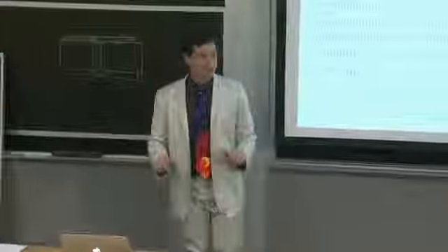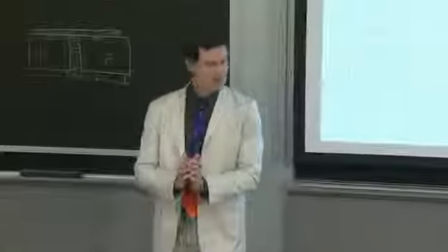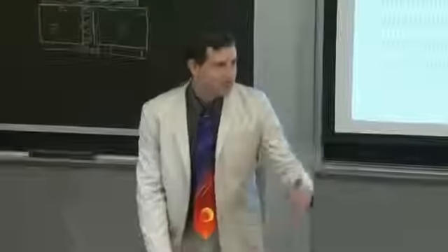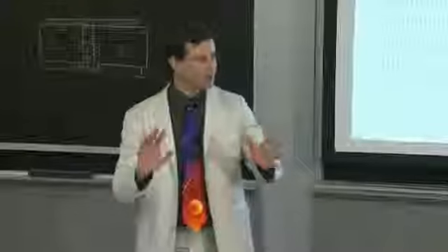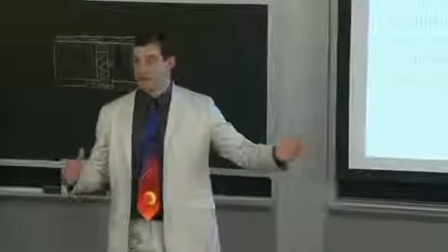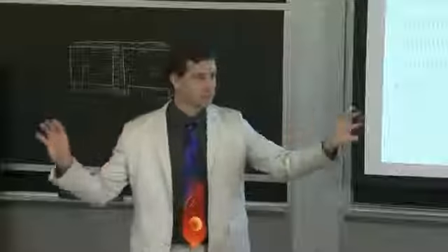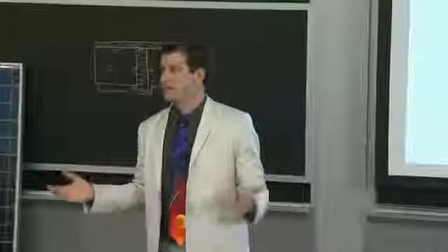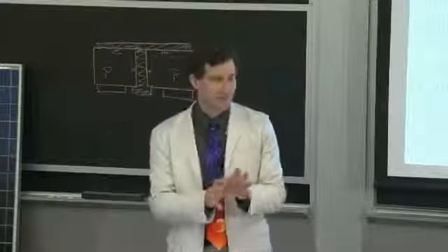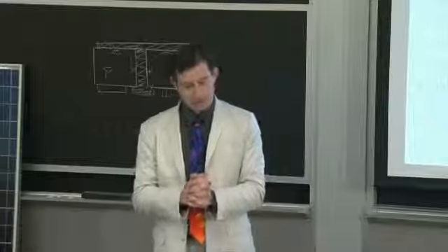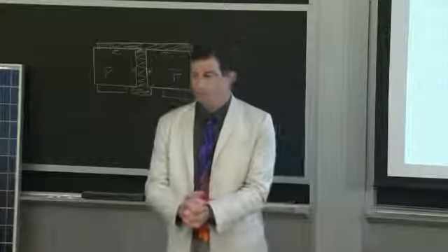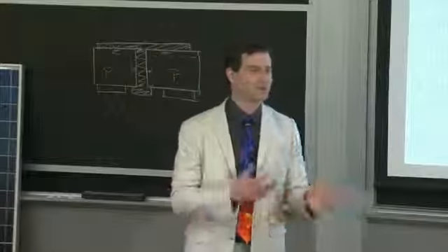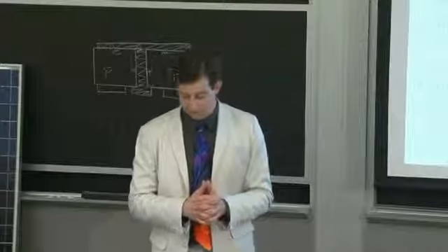Potentially. So if you have an inverter, how many people know how long an inverter lasts before it needs to be replaced typically? 5 to 10 years. Now it's up to, say, 7 to 12. But yeah, somewhere in that range, less than the 20 to 30-year lifespan of your array. And so now if you have these distributed little inverters across every solar panel, and they fizz out after a certain amount of time, somebody has to go up there and replace them. First, identify where they went down, and then replace them. So microinverter longevity is an important part of reducing risk and marketing inverters. So the microinverter community is helping to push or improve the quality of inverters over the entire solar spectrum, which is kind of cool.